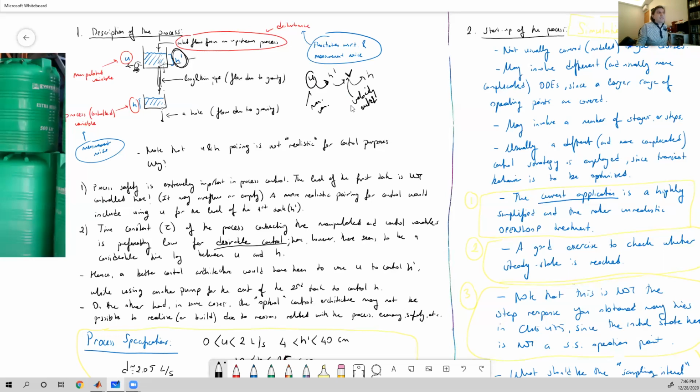So the outlet velocity from the tank is going to be a function of time even at the same height value. So it's going to be another first order, at least a first order process. Actually, we have v squared in our friction equation, right? Go to the Fanning friction factor in your fluid mechanics courses. You are going to see that it's going to be a nonlinear differential equation, and there is also nonlinearity buried here.